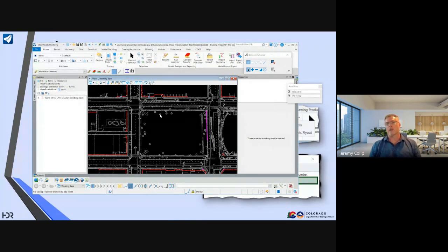I don't want to put a terrain file in here, because if I'm in a geometry file and that geometry is associated to the terrain, that terrain has to exist within that geometry file. So I want to make sure that these are non-data related. The hydraulics I have in there because if I'm a roadway, I'm not connecting the drainage to the roadway. If I'm in a drainage, I am connecting. So it's kind of understanding what some of those elements are.